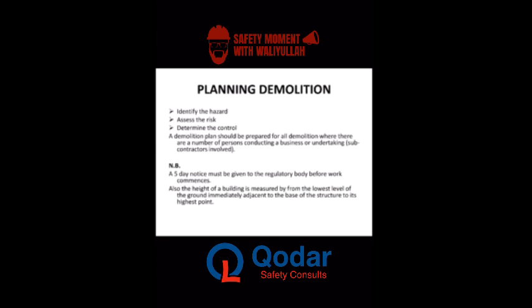Knowing that this is a high-risk job, it is advisable that we plan properly for demolition. Like we said earlier, in carrying out any task, we need to ensure that a risk assessment is done. We have to identify the hazards and the risks involved. We also have to determine the control measures that will be put in place. When embarking on a demolition, it is always advisable that we give a 5-day notice to every regulatory body that will be present before the work commences.